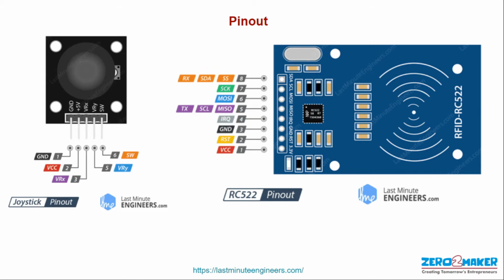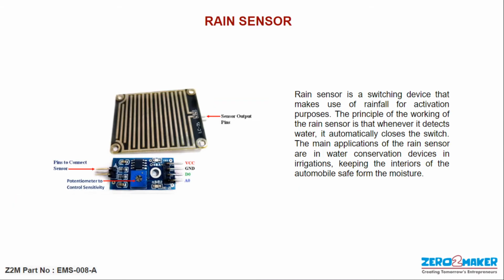Now we will be checking all the different kinds of sensors which we talked about. This is the rain sensor. It works on the physics of resistance. These are some conductive lines. Once the water is there, it finds that the resistance is low now, so it detects the rain accordingly.